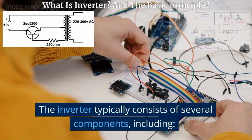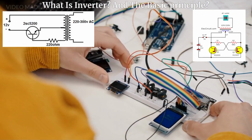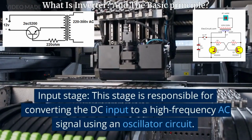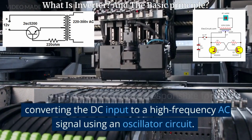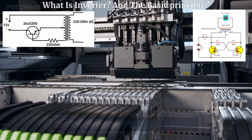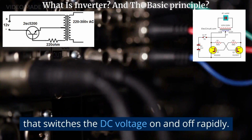The inverter typically consists of several components, including the input stage. This stage is responsible for converting the DC input to a high-frequency AC signal using an oscillator circuit. This circuit generates a square wave output signal that switches the DC voltage on and off rapidly.